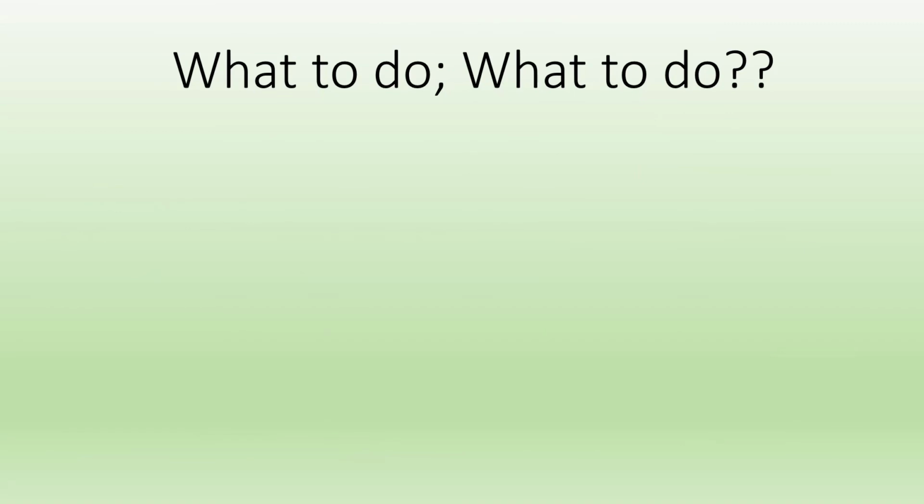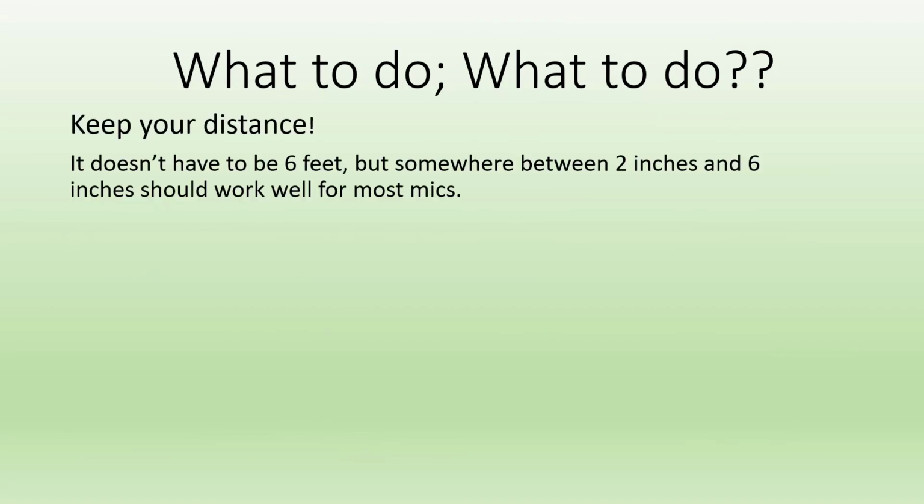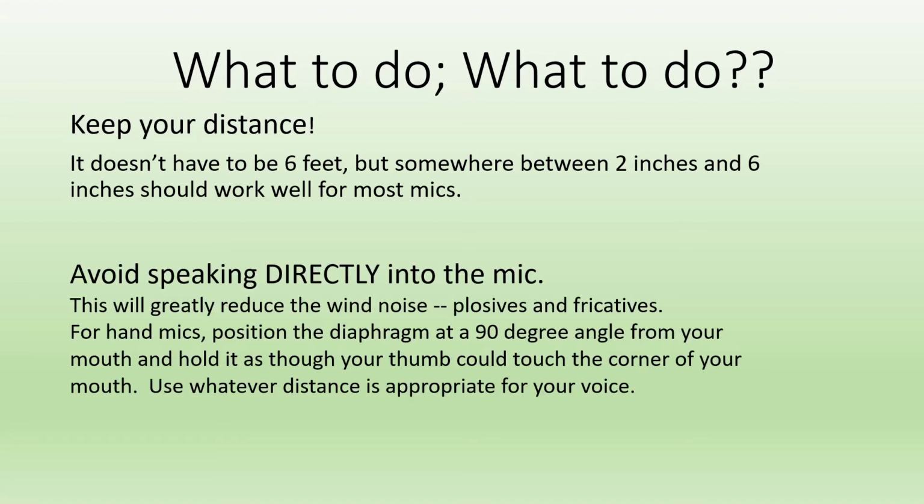What to do? Well, let's start by keeping your distance. Well, it doesn't have to be 6 feet, but somewhere between 2 inches and 6 inches should work well for most mics. Most importantly, avoid speaking directly into the mic. This will greatly reduce the wind noise, plosives and fricatives.